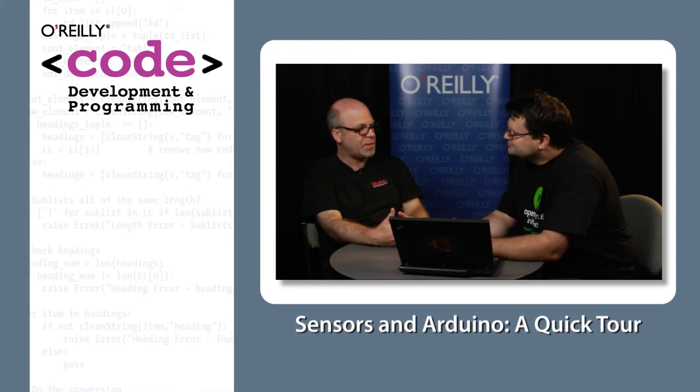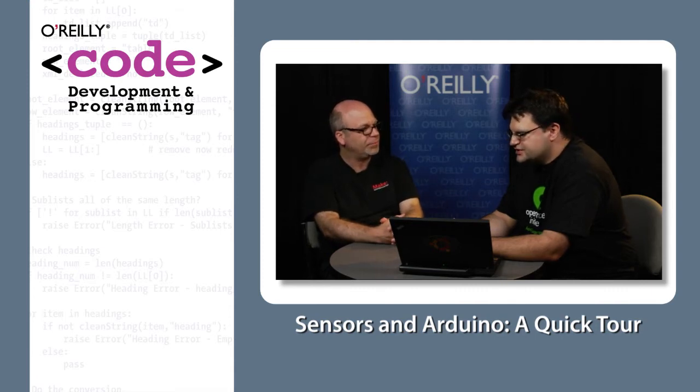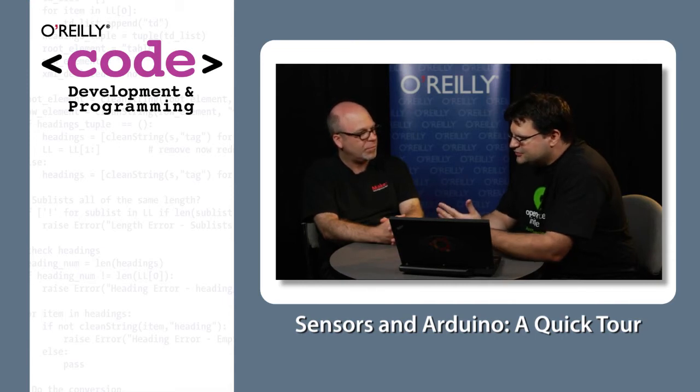Right. So is that the same thing as a force sensing resistor? Or does that mean you have to do more math? Are there sensors that will return a weight value? There are. You could use a force sensing resistor, but it's probably more expensive and more fragile than you would want in that case. Probably a piezo would be better for that sort of scenario.